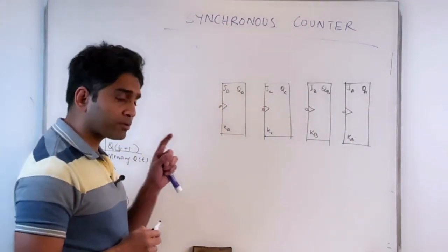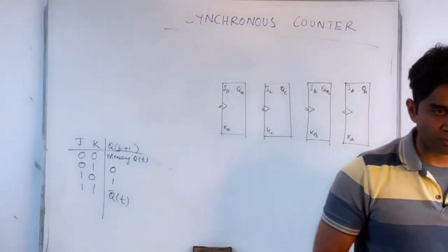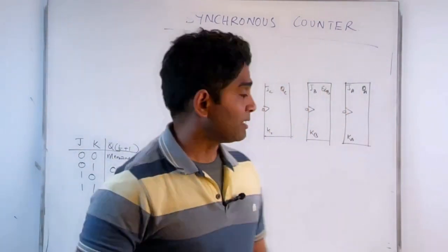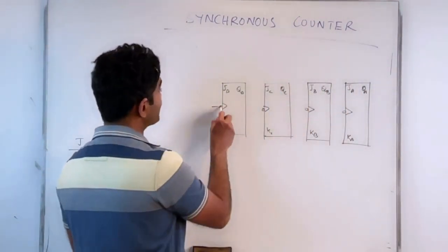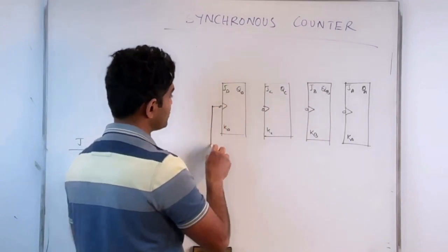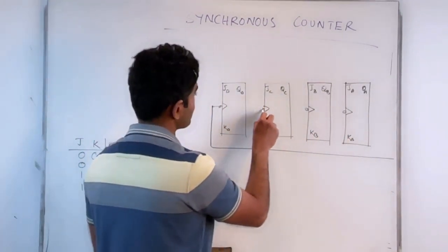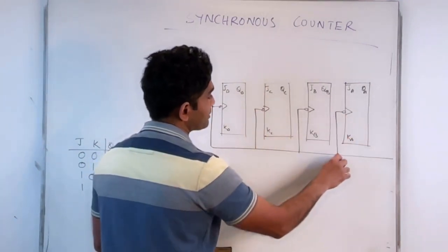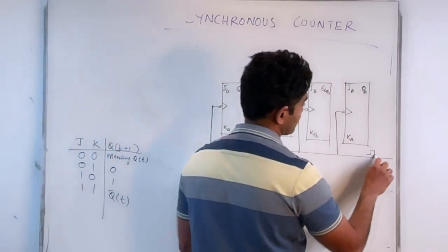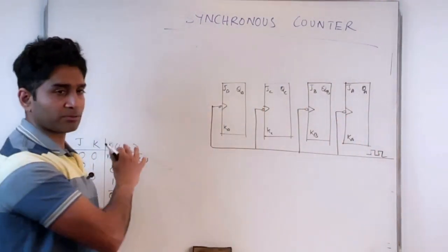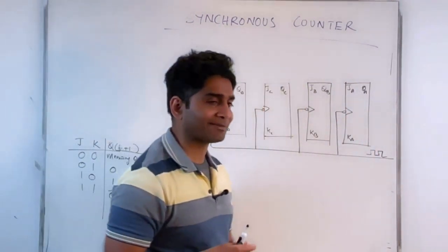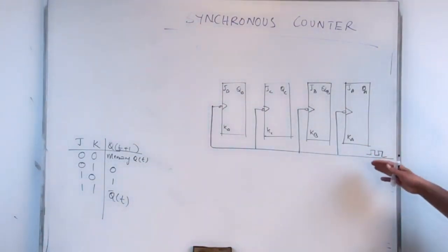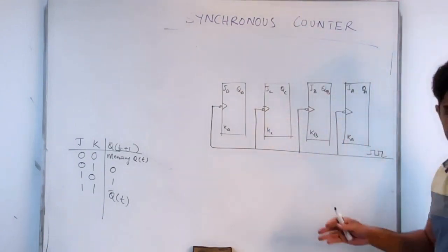Now, because I want this to be synchronized with the master clock, that's why we call this the synchronous counter. I start with ensuring that each of my flip-flop stages is driven by the master clock. And then I can do any modifications or additions to the circuit to make it work according to the specifications. So that's the clock applied to each of my flip-flop stages. So I don't have to worry about desynchronization here anymore. Every stage is synchronized with the master clock.